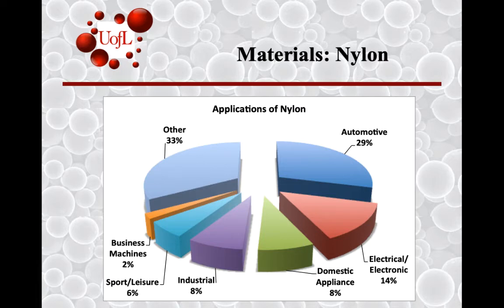And then of course after that it breaks into a bunch of different other options. Okay. So just in terms of looking at nylon, and within nylon itself there are a range of molecular weights, a range of chemistries, and a range of fillers that govern specific attributes in terms of density, cost, operating temperatures, and so on. Right? And there are some variants that can be cast as well.